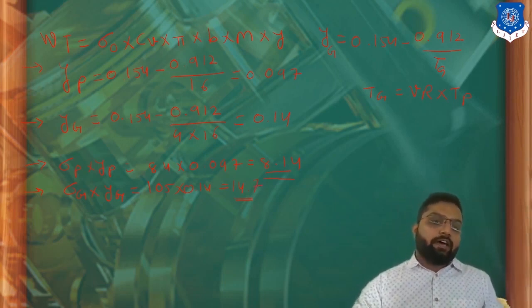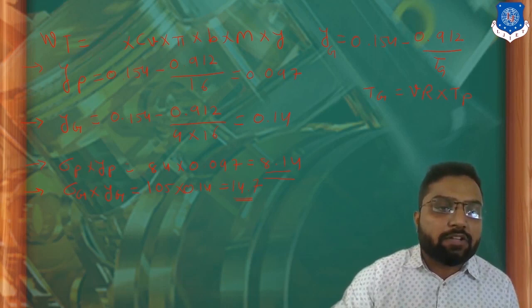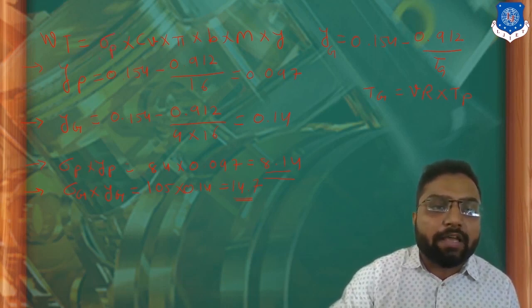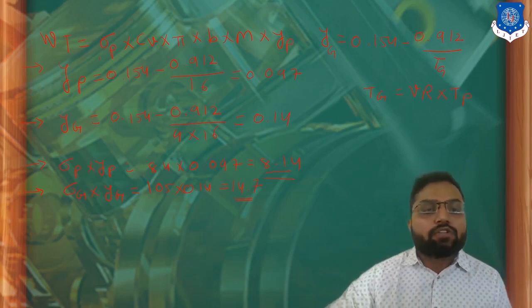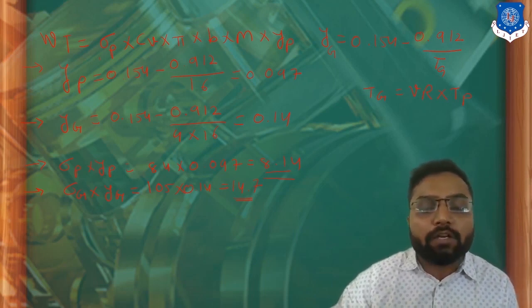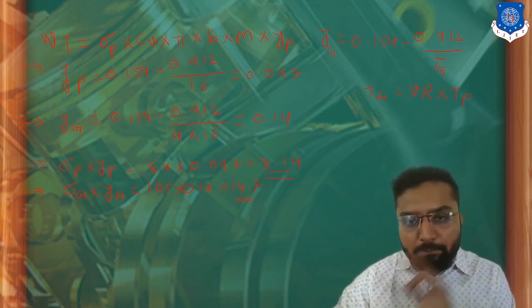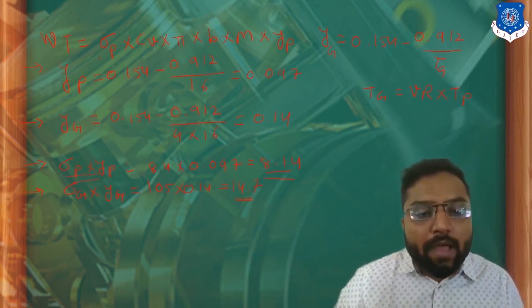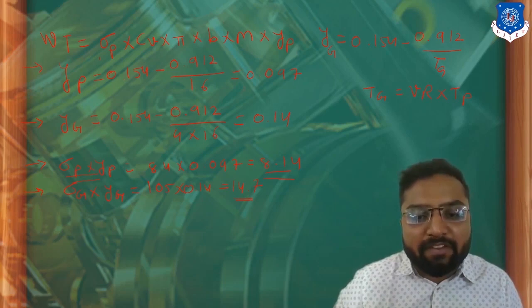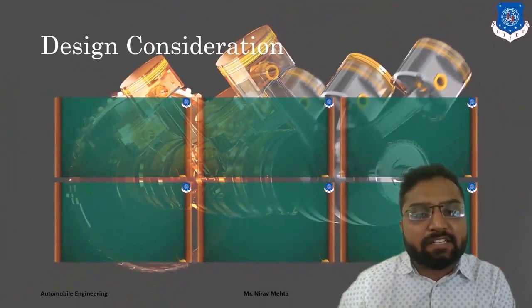So in this case, sigma 0 is going to be sigma p, and y will be yp. So the thrust force will depend on the design of the pinion. Why pinion? Because according to this condition, the product of sigma p and yp is 8.14. Okay, so let's move on to the next thing, which is determining WT.